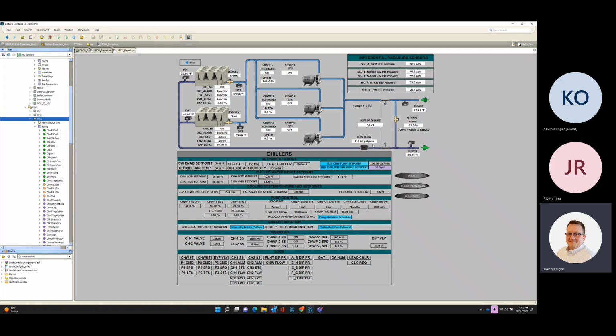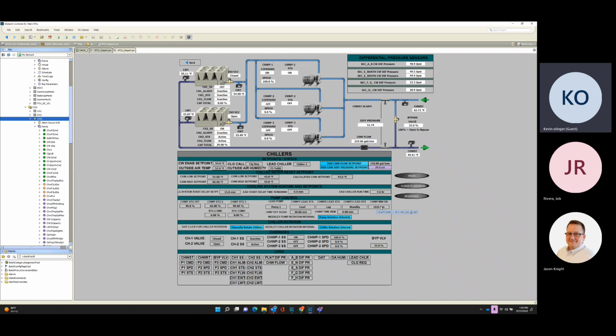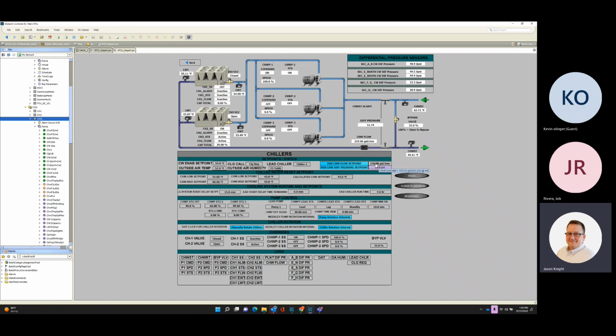Yep. And then just to cover our butts, we put the plant pressure sensor in there as well. If there were a tap at the machines that I could see across the chiller bundle, I guarantee you'd see it tripping at probably down to 142, 143, sorry, not pounds, but 143 GPM. If you had pressure sensors, you'd probably see it dropping below 6 pounds. So this is going to be our minimum right here.